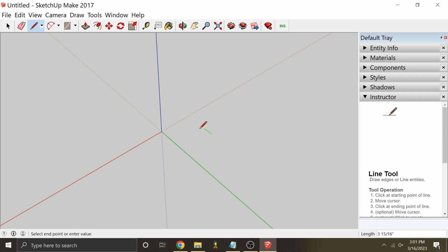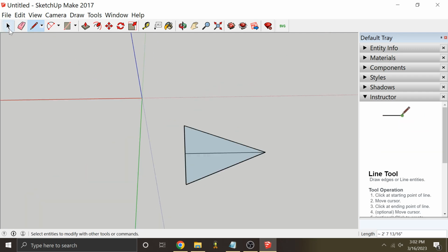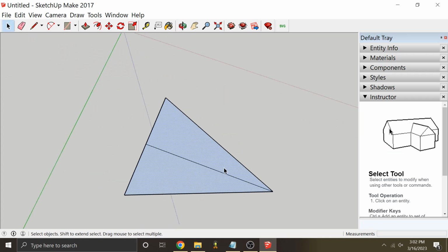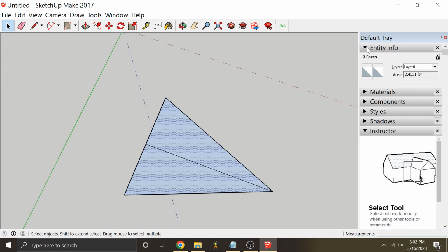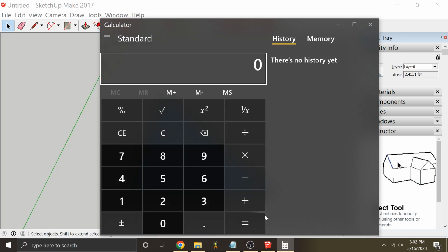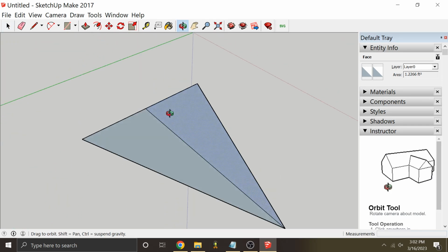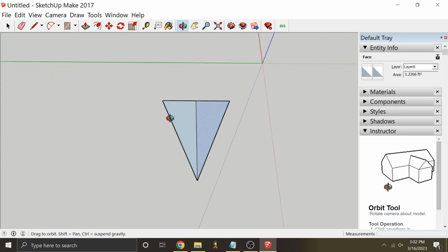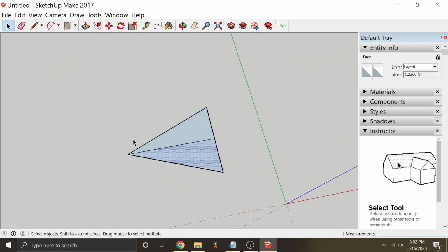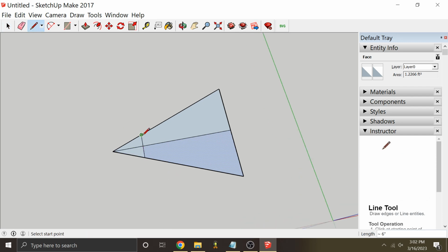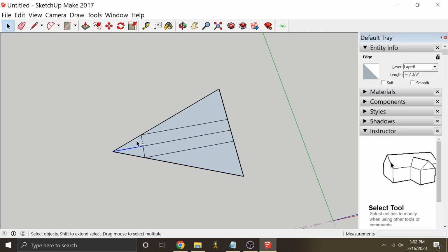So anyways, let's get started on our wing here. So that's fairly low aspect ratio, greater than 45-degree sweep at least. Yeah, so that's 2.45 foot squared, which is, yeah, so that's the 352 square inches we need. And I'm looking at this and I'm thinking it could probably be a bit lower sweep. And you also have to consider that the fuselage is going to take up some of this area here. So this area won't get included in the wing area.